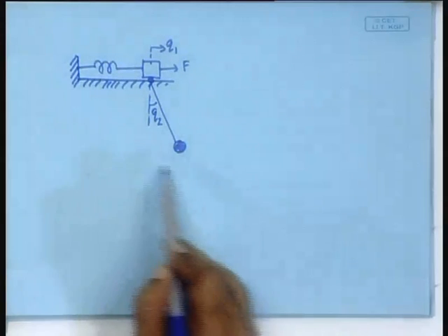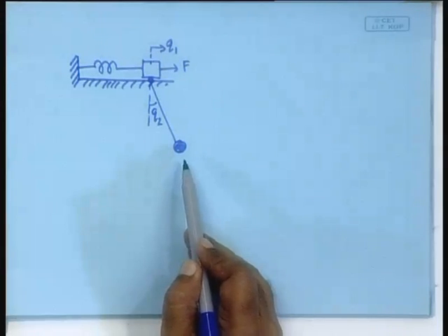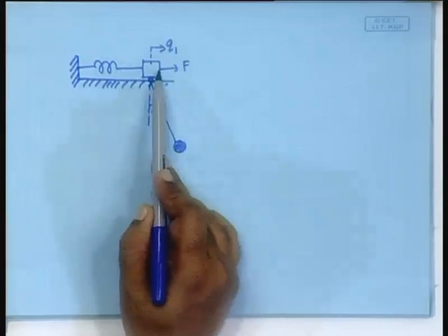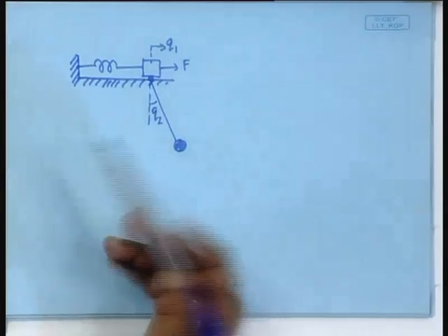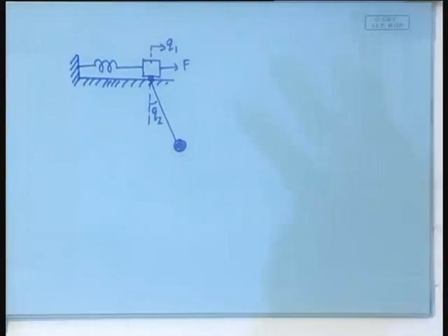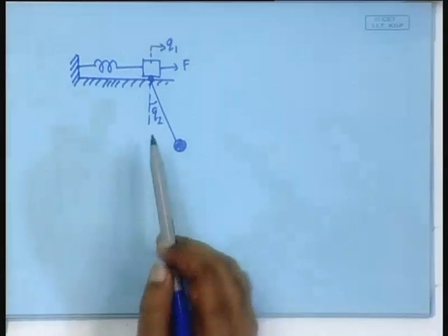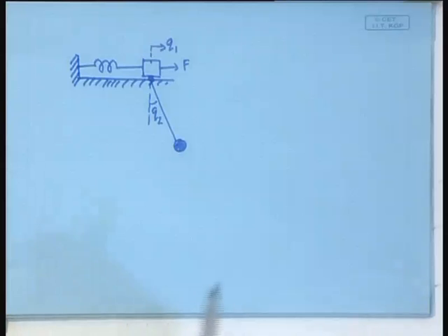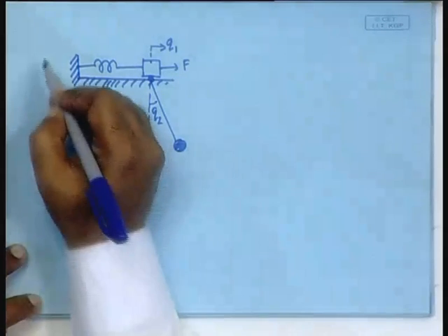Does it uniquely define the positional status of the system? Yes, it does. Notice that one is a translational variable, another is a rotational variable. Generalized coordinate, that is the concept of generalized coordinate. Whatever you want to define as the minimum number of coordinates that defines the positional status of the system, fine. Okay. Now, can you write down now the kinetic energy and the potential energy of this fellow with respect to q1 and q2? Try this, it will be good. So, this was problem 5.